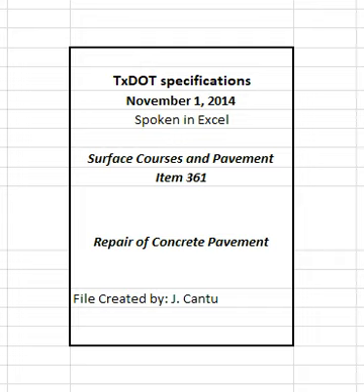Match the grade and alignment of existing concrete pavement unless otherwise shown on the plans. Concrete pavement may be open to traffic when specified strength is achieved. 4.2 Full depth repair. Repair areas identified by the engineer.